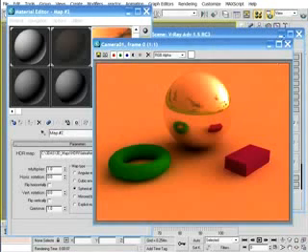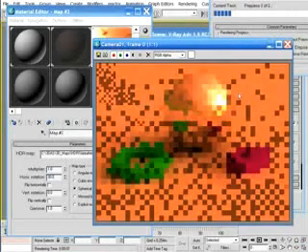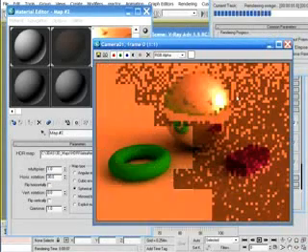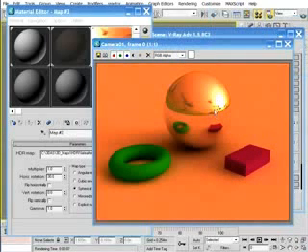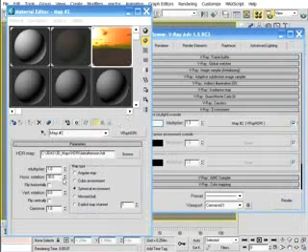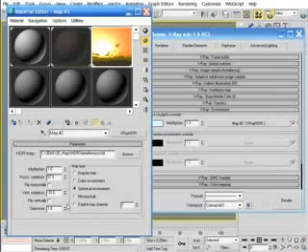So all I'm going to do now is apply some horizontal rotation, 30 degrees. And there in my sample slot the HDRI rotates. Now when rendered, here's what I get. The sun is clearly in a new location, as are the shadows. So if I keep applying horizontal rotation, my sample slot reflects all these changes. Likewise, I can rotate the HDRI vertically, but doing so is just not as necessary as applying horizontal rotation.